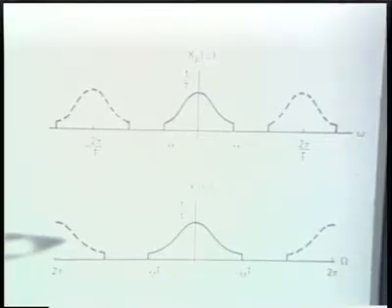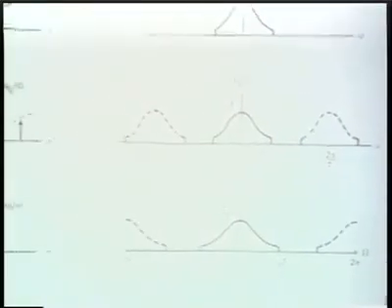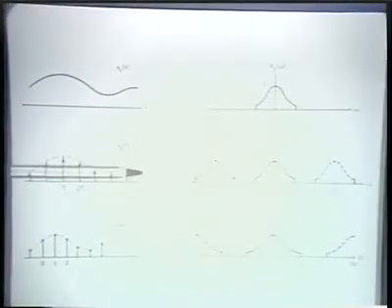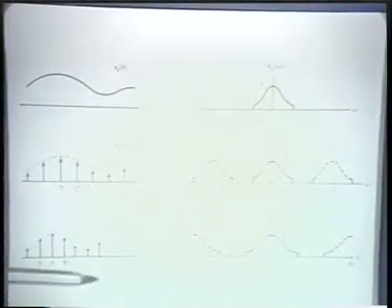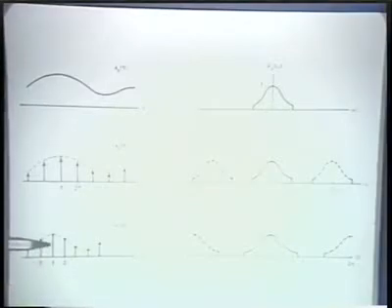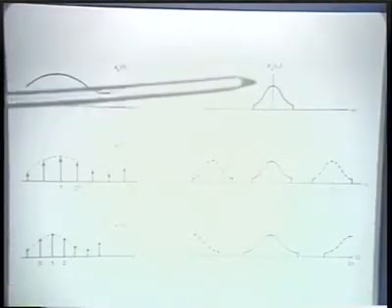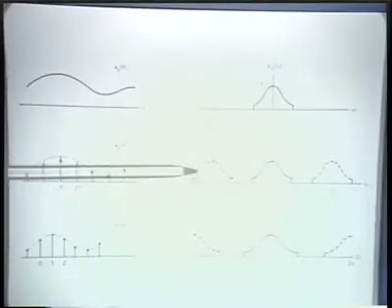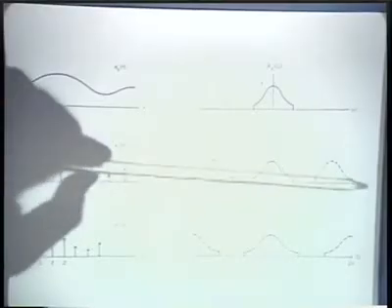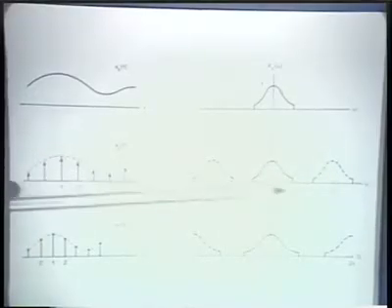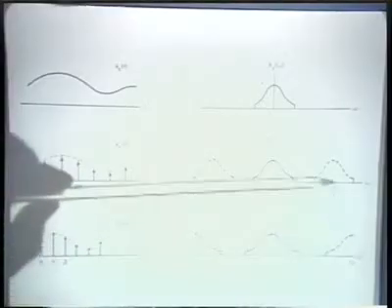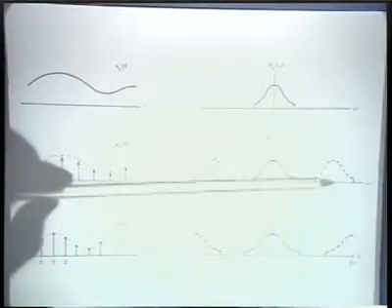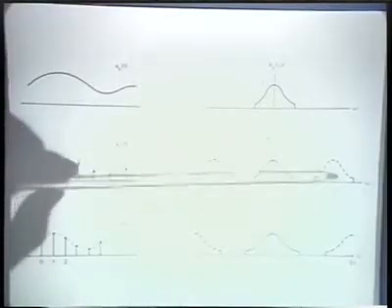So just looking at this again, and perhaps with the overall picture, in the time domain, we've gone from a continuous curve to samples, relabeled those, and in effect implemented a time normalization. Correspondingly, in the frequency domain, we have replicated the spectrum through the initial sampling process and then rescaled the frequency axis so that, in fact, now this periodicity corresponds to a periodicity here which is 2 pi and here which is the sampling frequency.